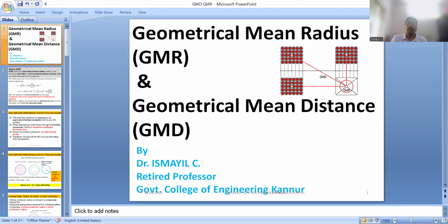In this case for AB, I'm getting it as 4.99. So if you consider this Y and B, here also it is mistakenly marked as R. It's not R, it is B. So Y and B is again the same calculation, so nothing to repeat. It is a symmetrical configuration. So by symmetry, DBC is equal to DAB. So it's again 4.99.